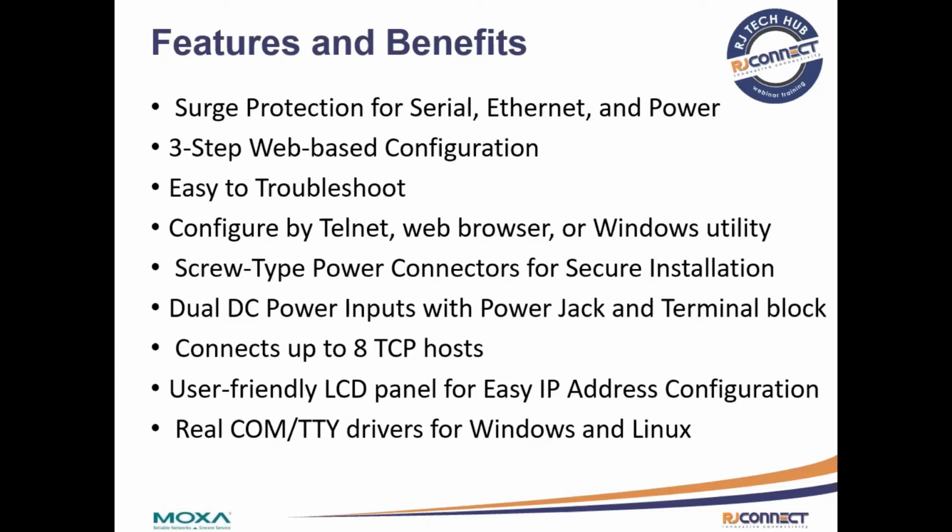This device supports SNMP, which can be used to monitor all units over the internet or over the Ethernet network. You can also configure it by Telnet, web browser, or Windows utility using the NPort search utility or device search utility, which you can download from the Moxa website. It also comes with a screw type power connector for secure installation.